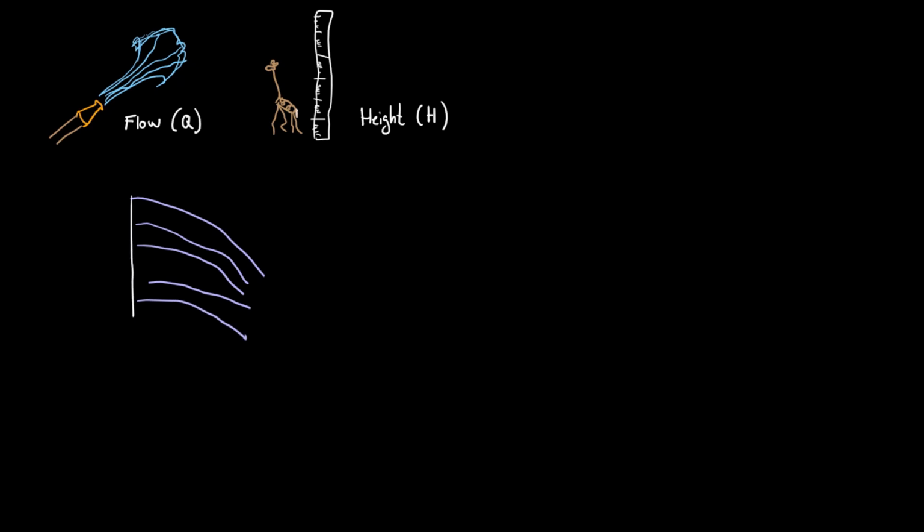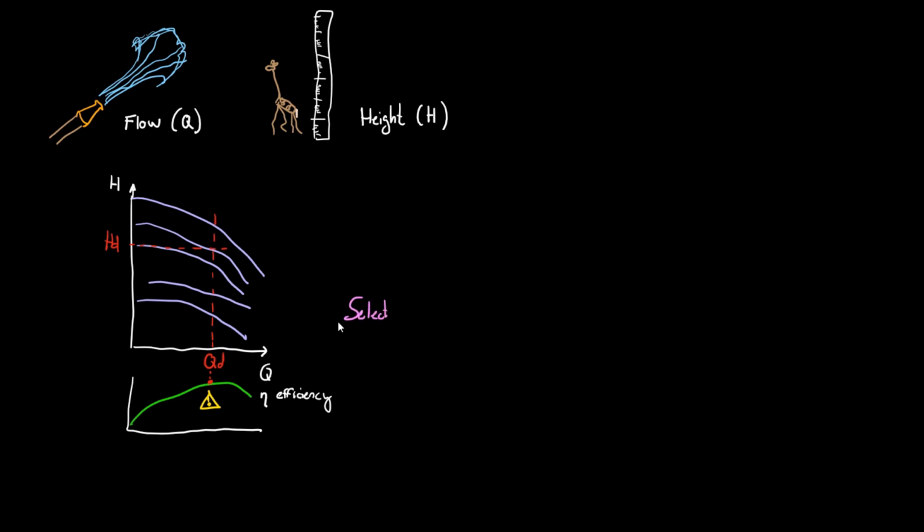There are two main parameters that you can tweak in a pumping system: the flow and the head or height. They define the working point of the pump. Even if you're using a computer program or a web-based service to size your pump, you will still need to come up with them beforehand. It is by affecting these two parameters that we gain leverage over our pumping system to make it more efficient. Once defined, you or the program will choose the pump with the best efficiency among all the ones that work in that working point. Let's start with the flow.